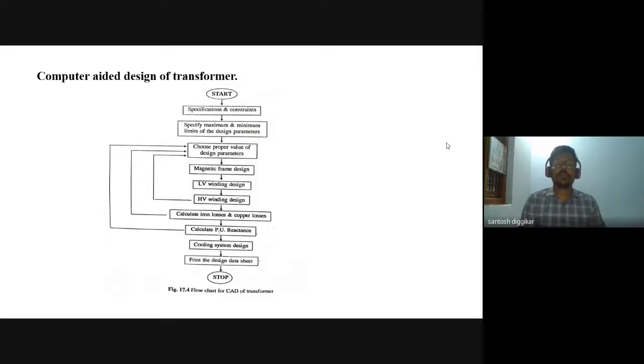Then computer design of transformer. This is a flowchart for computer design of a transformer. The same thing: specification, constraints, starting point, specify maximum and minimum limits of design parameters. What is the maximum temperature limit, minimum temperature limit, maximum losses, specify those things. Then choose proper values of design parameters and assumptions: specific loadings, magnetic loadings, space factors, and all that. Assume those things. Then design the magnetic frame, LV winding, HV winding, then performance check: calculation of iron losses and copper losses, calculation of efficiency, reactance, regulation.